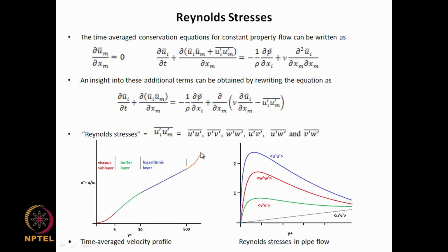Curvature is known to have a significant effect on turbulence stresses, and if you have stabilization by favorable gravitational head, then again you can have an effect on turbulence. So there are a number of specialized effects which are not captured properly by the k epsilon type of models, because you are not solving for all the 6 stresses.